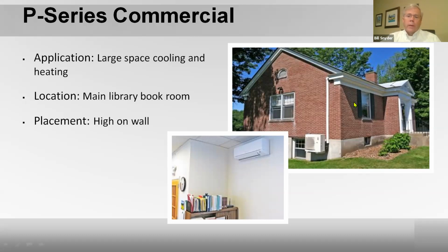I would recommend that you always have at least 16 feet of line if possible. Now, if you were in our training room, you'd see our equipment operating with probably 5 to 6 feet of tubing between the outdoor unit and the indoor unit. Extremely quiet. I don't hear any noise from them.